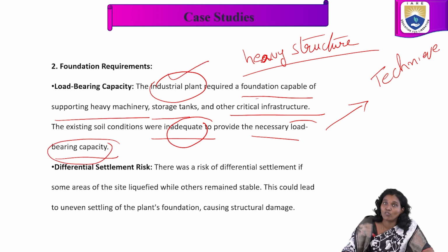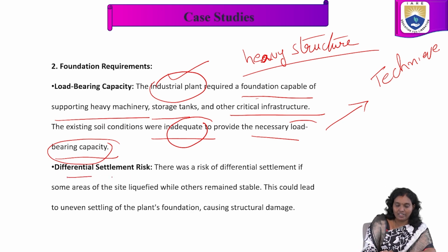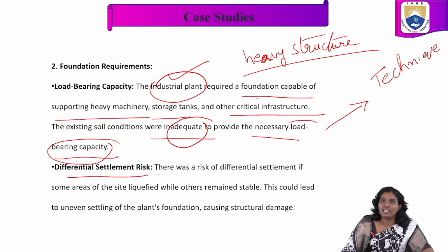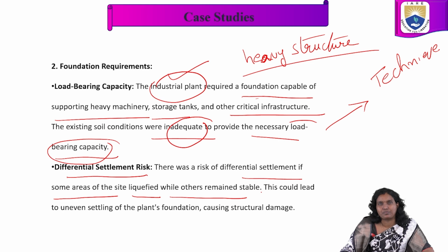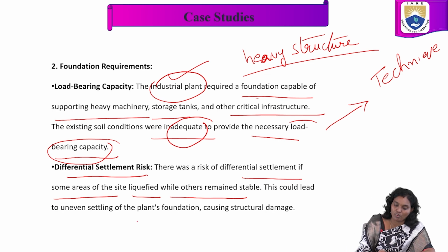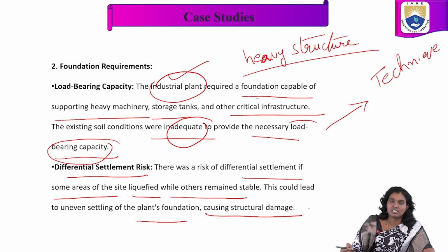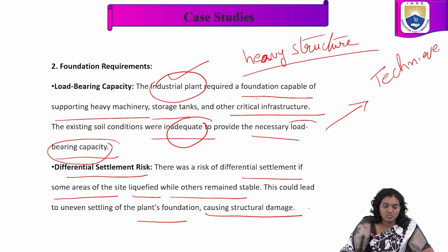It also involves settlement risk, here the differential settlement risk. There was a risk of differential settlement if some areas of the site liquefied while others remained stable. This could lead to uneven settlement of the plant's foundation, causing structural damage.